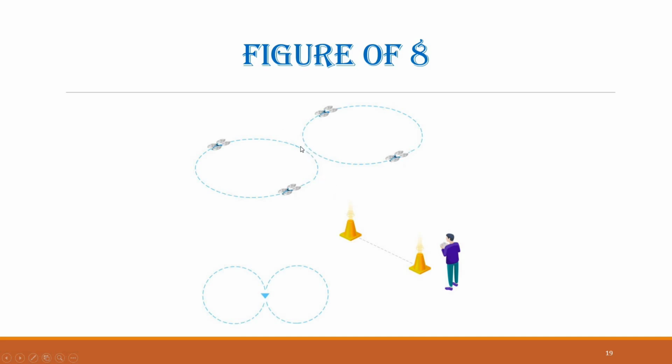To begin, follow the same initial steps as the Lazy 8 by moving just past the 90-degree point and guiding the drone toward the 6 o'clock position. Once there, apply rudder input and maintain it consistently as you move the drone in a circular path, while continuously pushing forward.